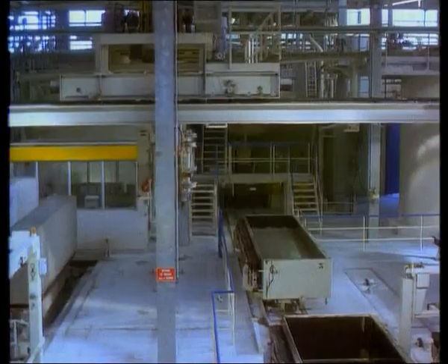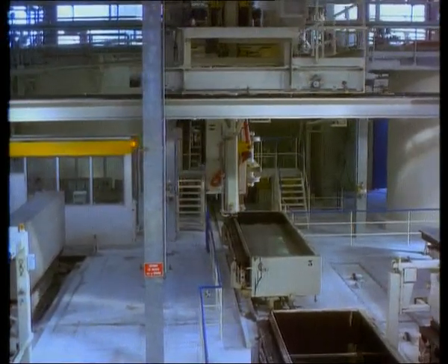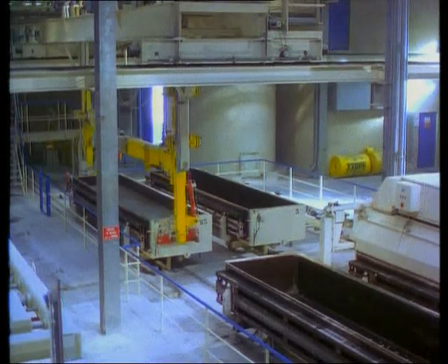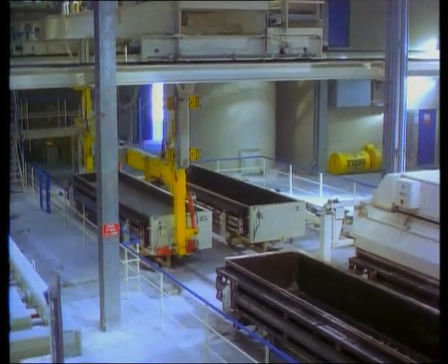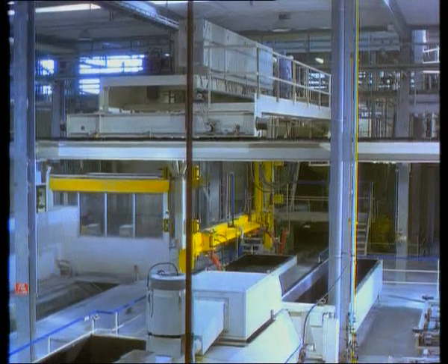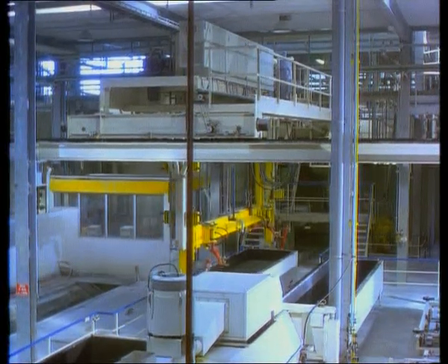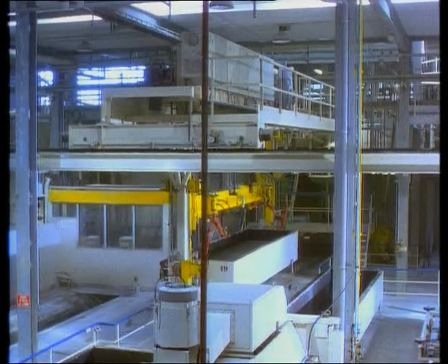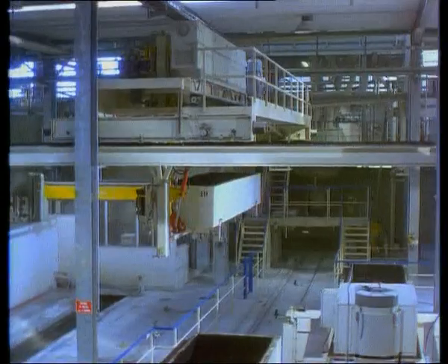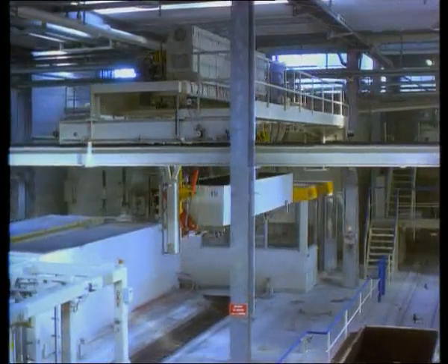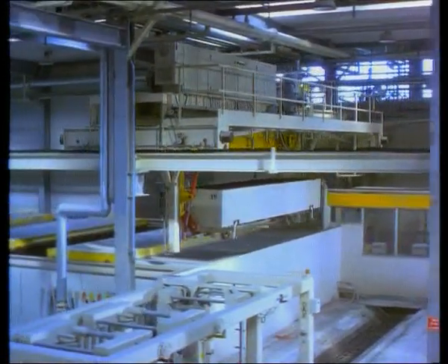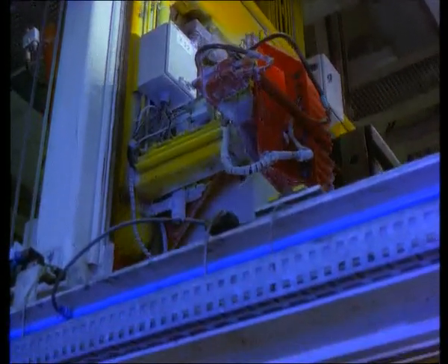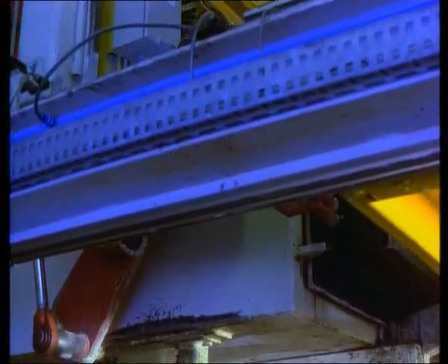One of the special features of YTONG technology is the tilting process. All transportation movements are carried out by a tilt crane. This tilt crane is a robust, fully automatic multifunction unit. It transports the freshly cast mold to the rising section and puts it down in a pre-selected rising location.